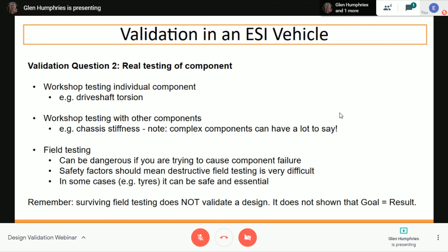At the other end, we support it so it can't move, but it can rotate, of course. We fit a lever arm to it, a lever arm of known length. And we hang weights off it, whether it's your dumbbells or your gym weights or sandbags or buckets of water, anything you have a good, accurate measure of the weight. Hang that off there, force, distance, torque, until it breaks. Just break it, you've tested it, beautiful.